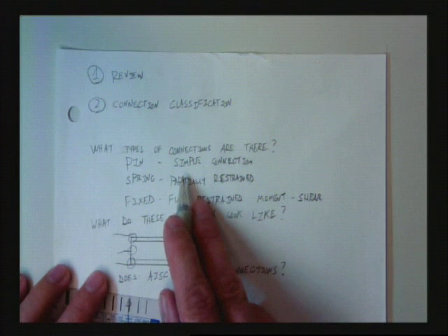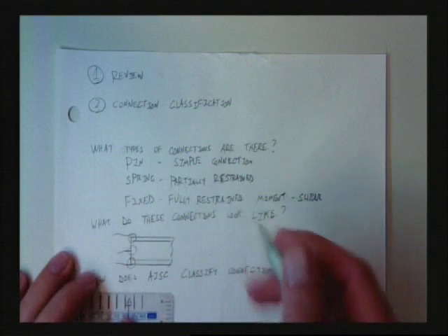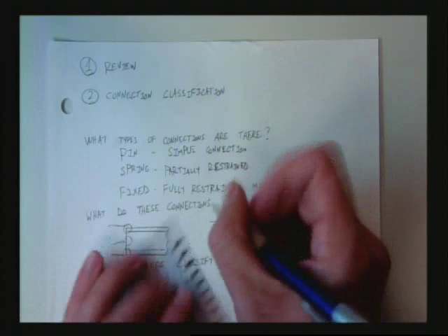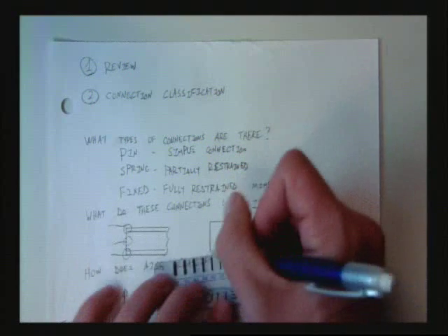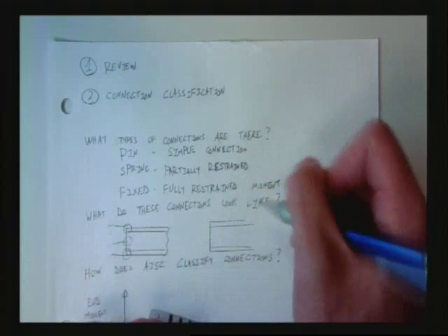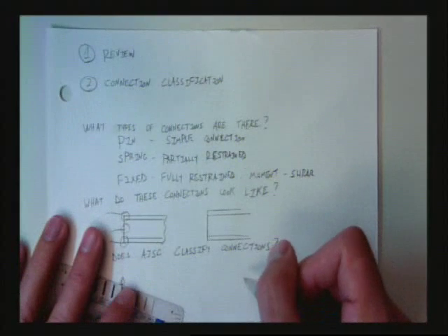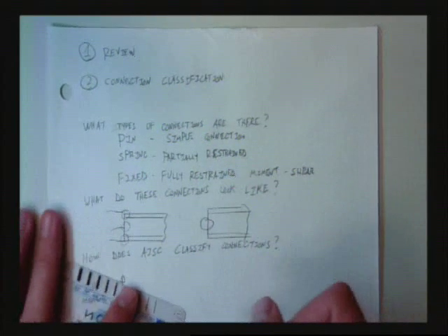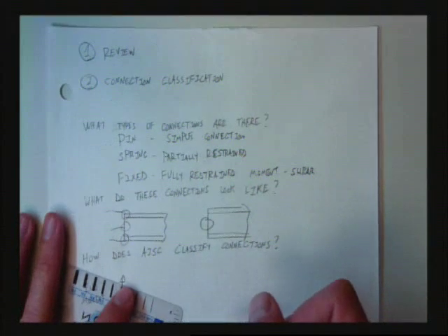Shear. Right. So when we think of a pin connection, where do we have to have our load transfer at? The web. That's right. The web. That's where we have to have our load transfer.